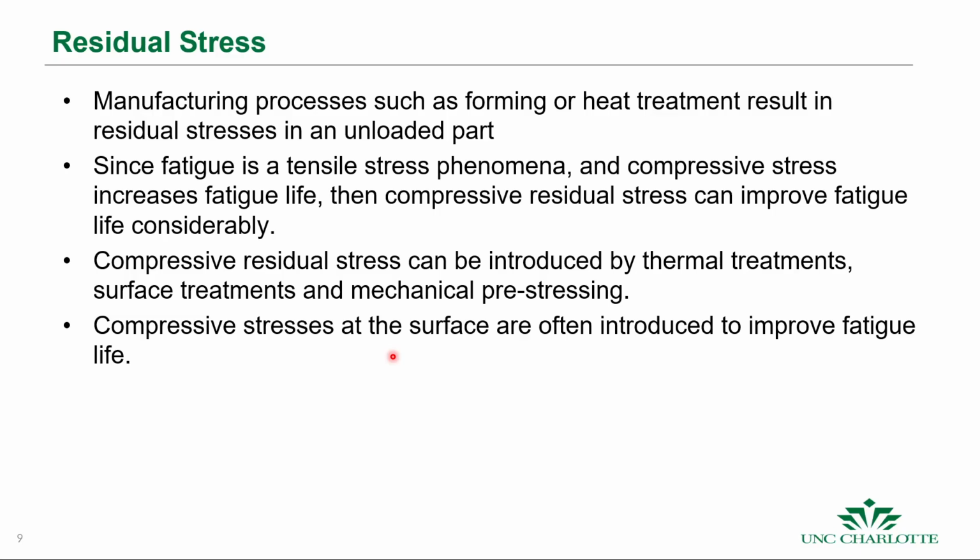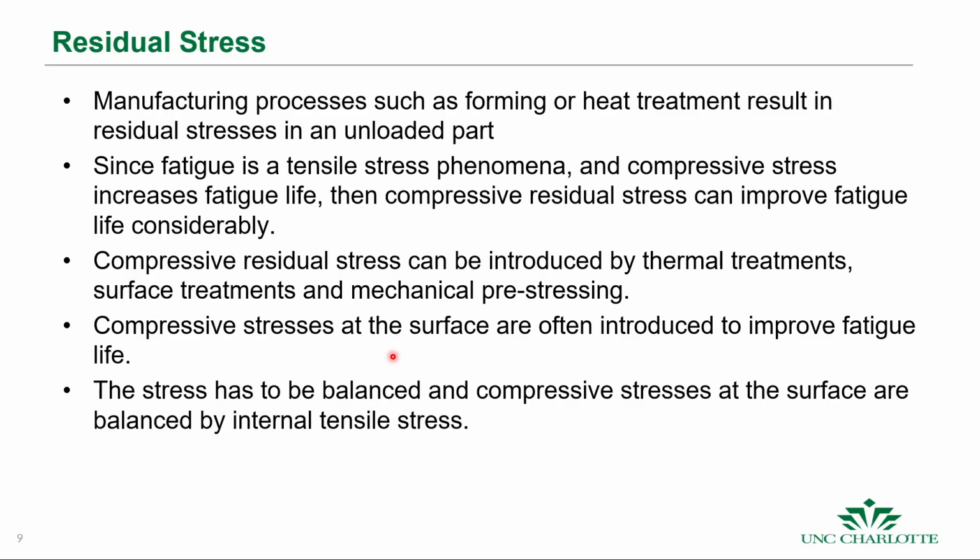Okay, this is a huge industry surrounding introducing these residual stresses. For example, shot peening is done for a lot of rotating machinery parts, gears, etc. So if we introduce compressive stress at the surface, though, that stress has to be balanced by some tensile stress inside the material. Okay, so we always have to have our forces balanced, and if we have compressive stresses at the surface, then we're going to have tensile stresses inside the part somewhere.